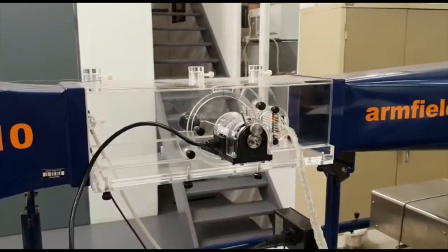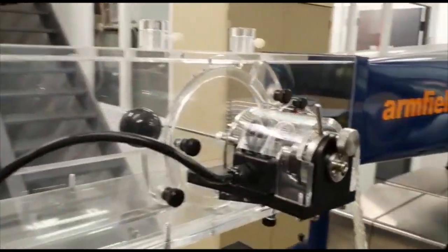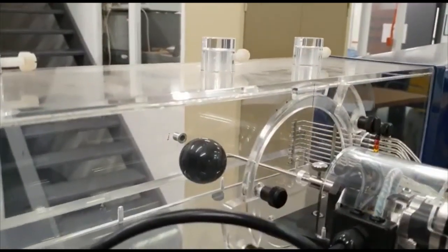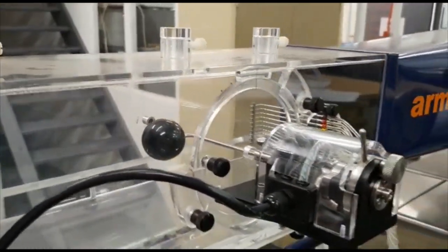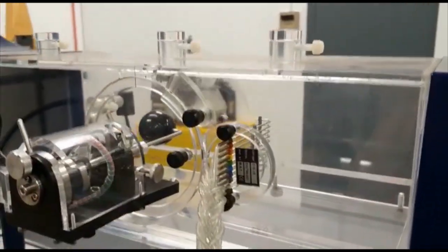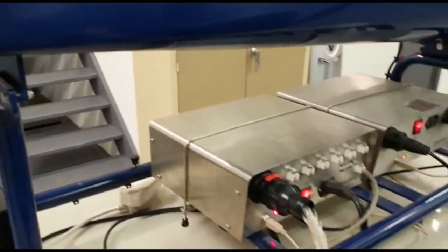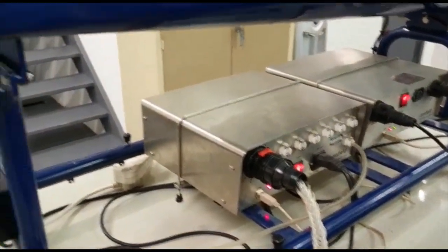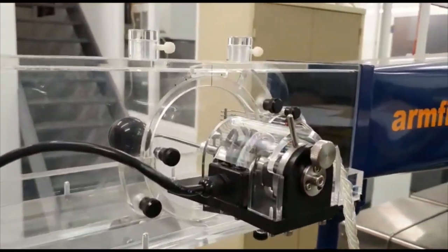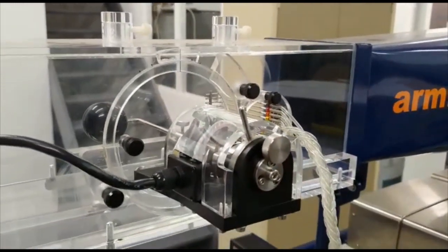For the second part of the practical, we're doing some force measurements. This is the force balance that we have attached to the small sphere on the inside of the wind tunnel, and at the back of the sphere we have the wake rake. The wake rake is again attached to the manometer that's taking the pressure readings. So we'll have two sets of readings this time, one for the forces experienced by the sphere and pressure readings for what is happening in the wake of the sphere.